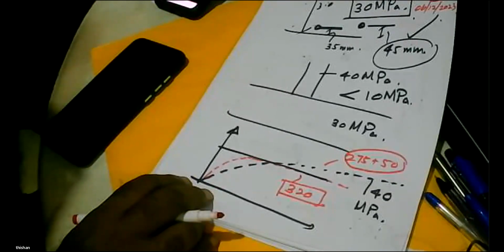Now 2 years have gone, you have cured it properly, you had fly ash to continue the reaction. If you take a core and see, the real concrete can be ranked as 45 megapascal cube strength concrete.